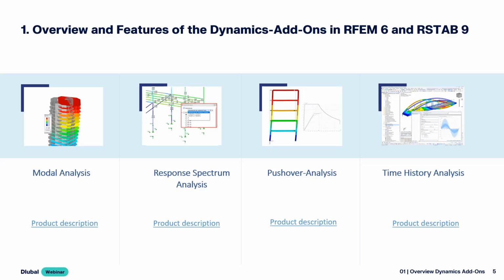Well, the 100/30 is more for the directions, but yeah. So in the end, we will get an envelope of internal force results, which can be used further for the design. Then we will go into the first nonlinear analysis, which is the pushover analysis.